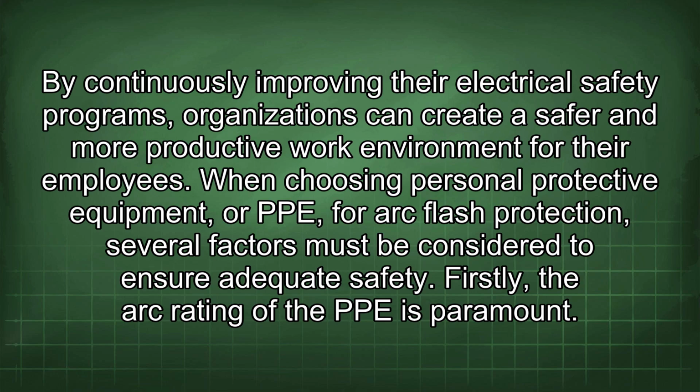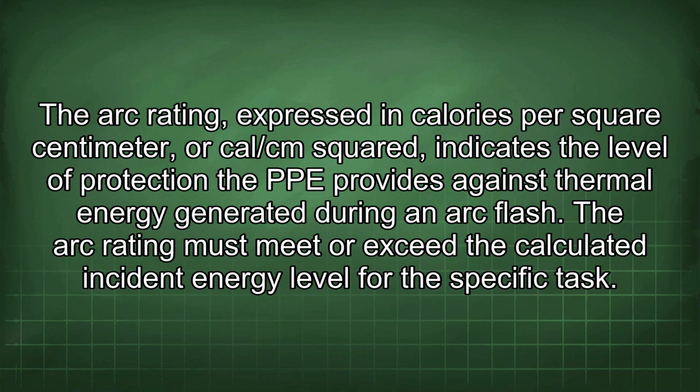When choosing personal protective equipment, or PPE, for arc flash protection, several factors must be considered to ensure adequate safety. Firstly, the arc rating of the PPE is paramount. The arc rating, expressed in calories per square centimeter, or cal/cm², indicates the level of protection the PPE provides against thermal energy generated during an arc flash. The arc rating must meet or exceed the calculated incident energy level for the specific task.